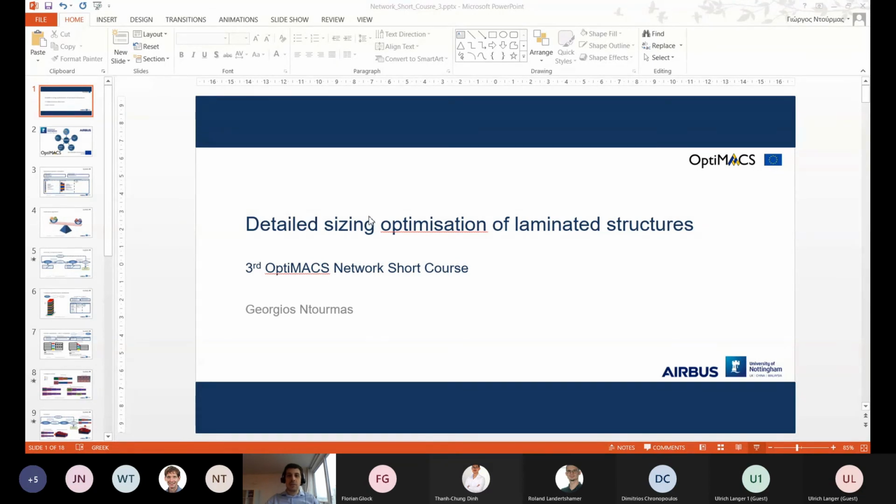As for the objective function of the problem, for this presentation, it's something as simple as a weight minimization of the structure, but we can also have other objectives such as a performance maximization of the aircraft, for example. Now, when it comes to constraints, they are split in 2 categories. I'm going to first start with the physical constraints. These are the classic structural constraints you would expect, such as strength, buckling, eigenmodes for the structure, for example, and